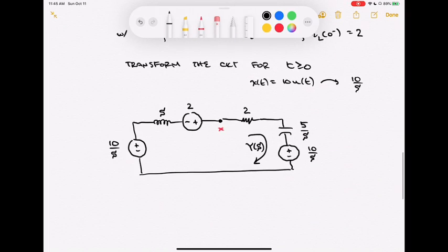That gave me a transform domain version of that circuit, which has a really neat advantage. Those 2 initial conditions now are explicitly incorporated into the circuit diagram. Those initial conditions show up as physical elements, if you will, and so they're much more directly used. It's much more difficult to somehow miss them or misuse them in this transform domain equivalent.